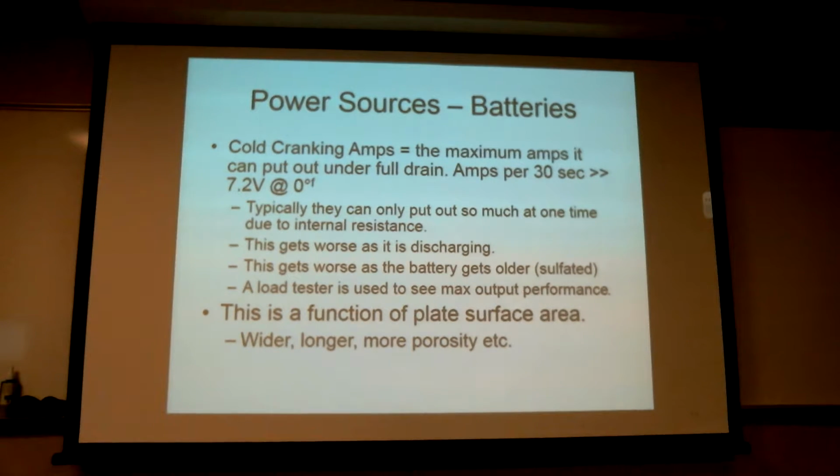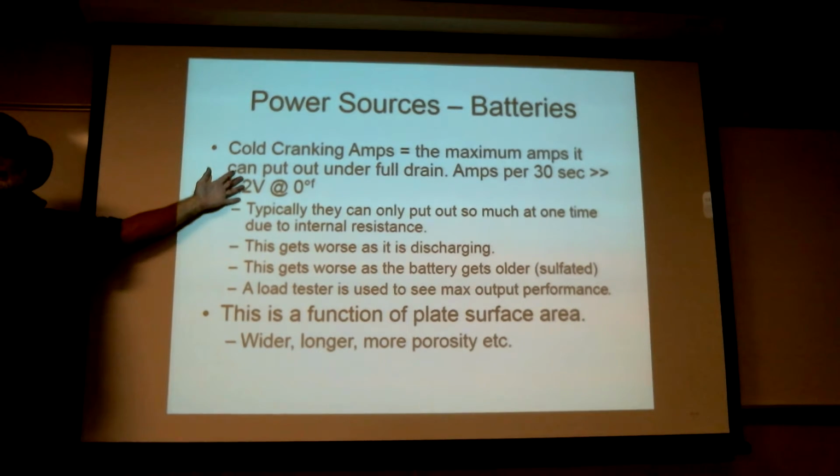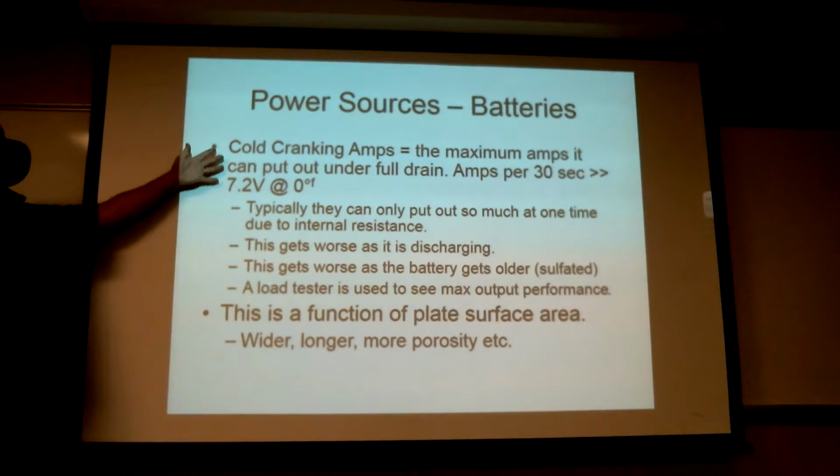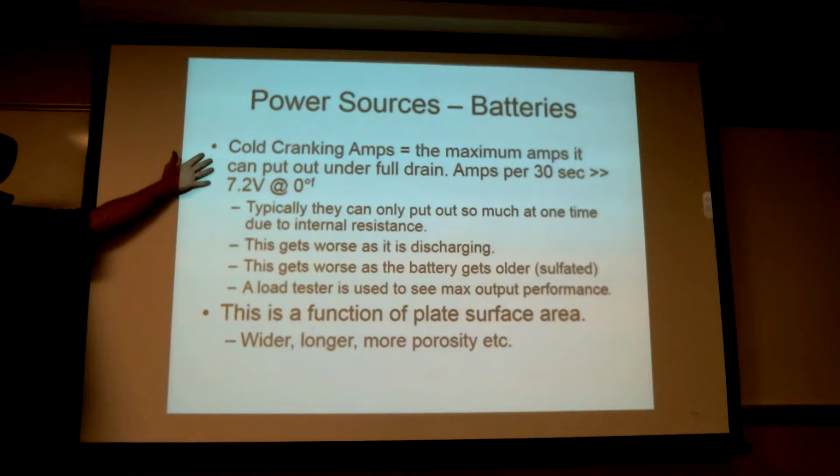The high amp hour is the deep cycle. High amp hour means it will produce more electrons. The parking lot's bigger, but it doesn't necessarily mean it can deliver them at a high rate. Okay, that makes sense, just for longer though. Typically, the idea is to make it last longer, but if it's a deep cycle battery, even though its cold cranking amps isn't 450, maybe it's only 225, I'd still bring it up to 225. Now it isn't going to last; it's going to last an hour or two.